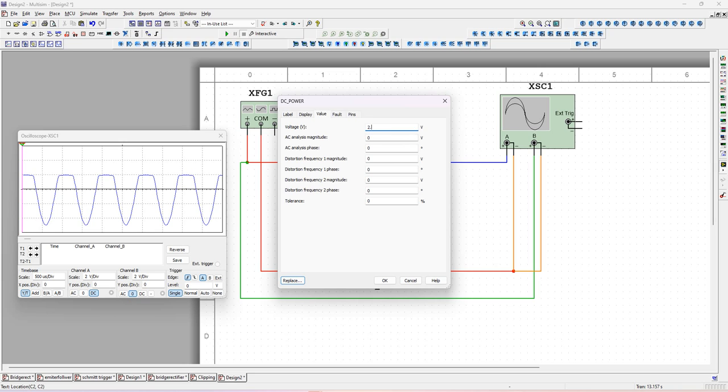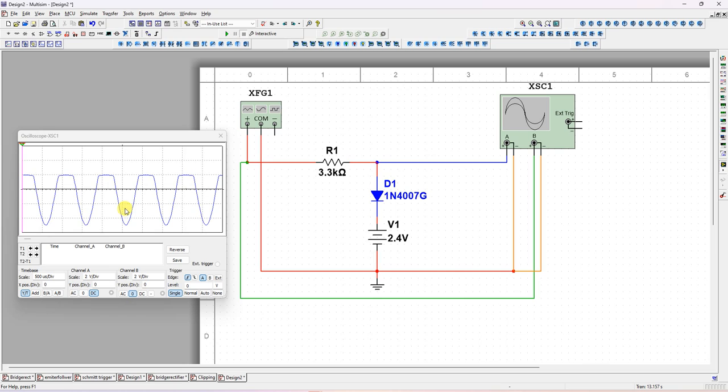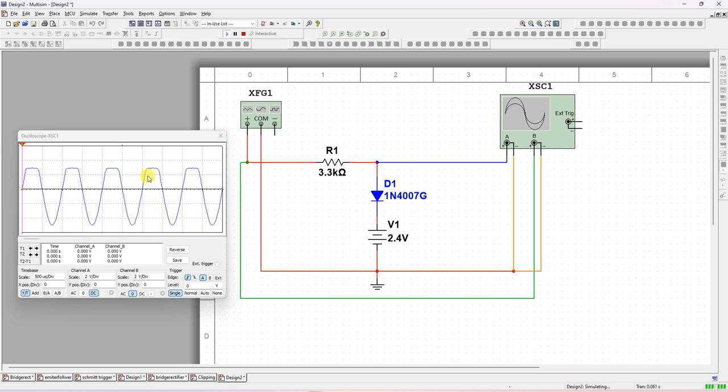So it will be converted into a 3 volts clipper. It is a positive clipper which will clip all the voltages above 3 volts. Below 3 volts it will allow. Now run this. See, now from here it is shifted to here.